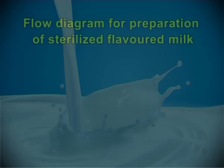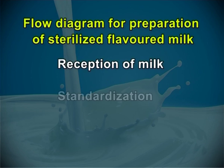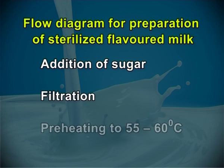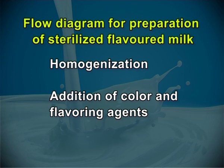Figure 2. Flow diagram for preparation of sterilized flavored milk. Reception of milk. Standardization. Clarification. Addition of sugar. Filtration. Preheating to 55 to 60 degrees centigrade. Homogenization. Addition of color and flavoring agents.